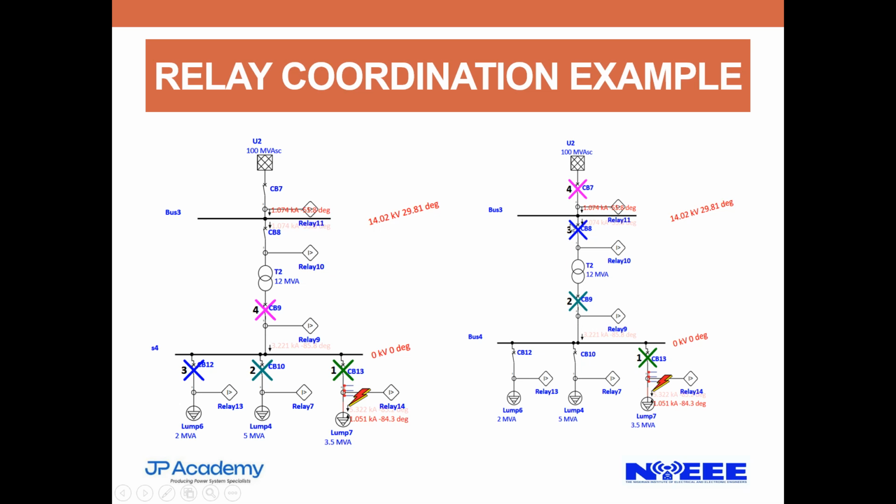Now, all these are not operating at the same time. On ETAP software, we can actually see the time of operation of each of the relays. So fault isolation is quite different from relay coordination. Fault isolation, the relay closest to the point of fault should be the one to be tripped. Relay coordination, okay, how would all the relays in the power system network operate, assuming one of them is faulty? That is relay coordination.